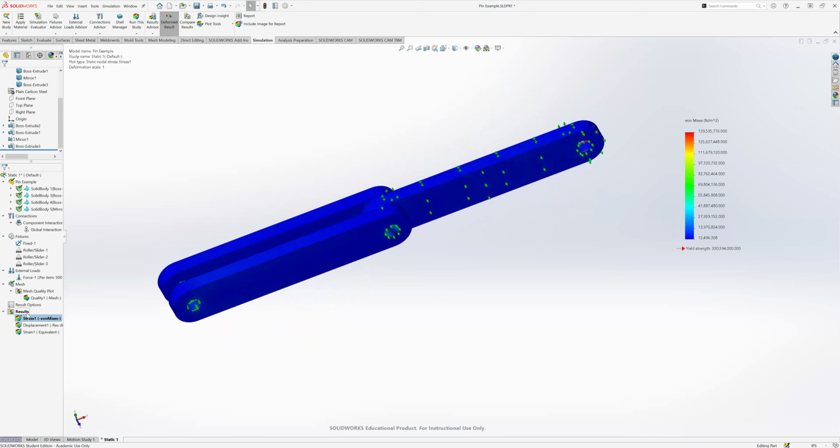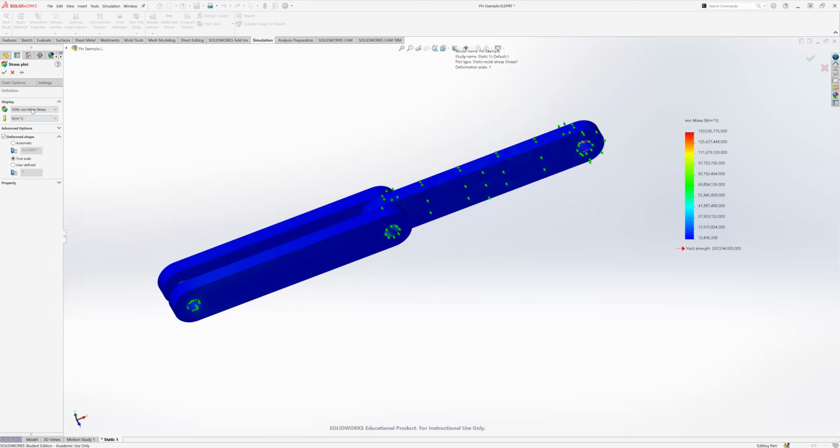Another thing you can do is go to advanced options, which is useful with separate bodies. Especially when you're doing multi-bodies or assemblies, it's really nice to be able to show the plot only on selected entities. In this case, I really want to look at this pin. Actually, not the pin, I want to do bodies. This is for faces, this is for bodies, and I want to show just this pin. That's a great way to look inside.